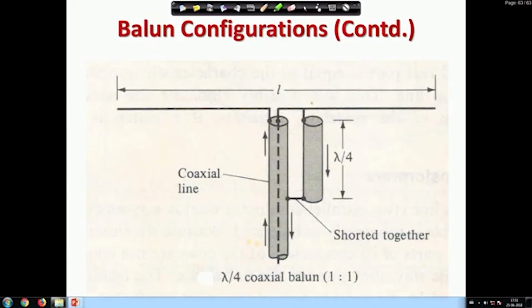So, if a dipole is directly used to receive, there will be a lot of reflection because it is a huge mismatch. So, can we have a dipole that behaves as a 377 ohm or 400 ohm radiation resistance? Actually, that problem will be solved by understanding this differential mode and antenna mode concept, but that is for a later lecture. Thank you.